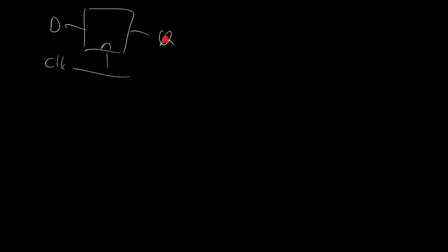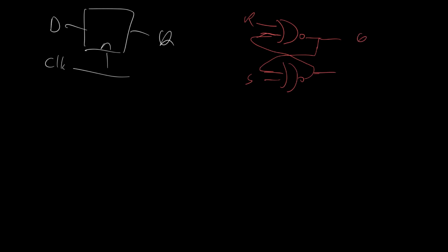We keep hearing that flip-flops can become metastable, and now we get to see that that really is the case and why that occurs. We have seen how to make a flip-flop, and the crucial part is our RS latch, which in this case I'll use 2 NOR gates. That's R, that's S, this is Q, this is Q prime, and we discussed this before in lectures, and we know that when both R and S are 0, then each of these looks like an inverter.